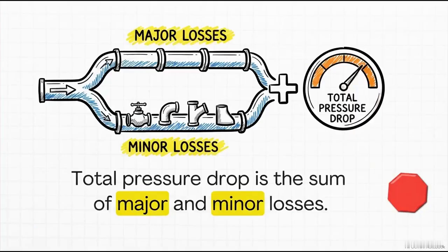Your total pressure drop, represented by delta P, is basically the sum of several thieves stealing energy from your fluid. First, you've got your major loss, which is just the sheer friction of rubbing against straight sections of pipe. Then you have minor losses. These occur every single time the fluid has to squeeze through a valve, turn a 90-degree corner, or pass a fitting. Finally, you have the equipment drop, as the fluid literally fights its way through things like heat exchangers or filters. You absolutely must account for all of it.